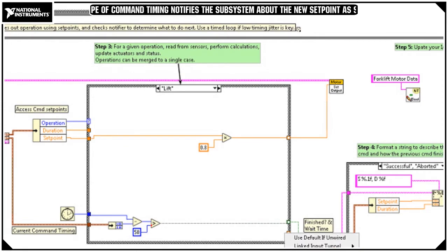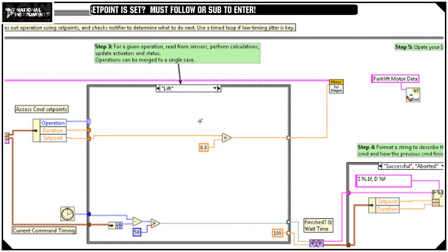And then drag that across. I can just drop a 100 here. This is the default wait time, and since our motor timeout is 100, we wanted to move on at least at that point. So we did that, great. That's all we need to do for our lifting mechanism, right? We just want it to take the joystick input and lift at a 0.8 rate of the motors.